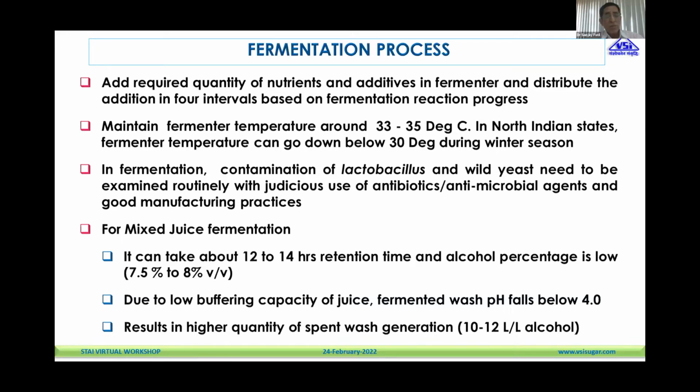In fermentation, contamination by lactobacillus and wild yeast needs to be examined routinely, with judicious use of antibiotics and antimicrobial agents and using good manufacturing practices. One can use mixed juice also for fermentation, but it will result in lesser alcohol concentration in fermentation broth of about 7.5 to 8%. But it will also take a vessel retention time of about 12 to 14 hours. But then, of course, your steam consumption in distillation will increase.